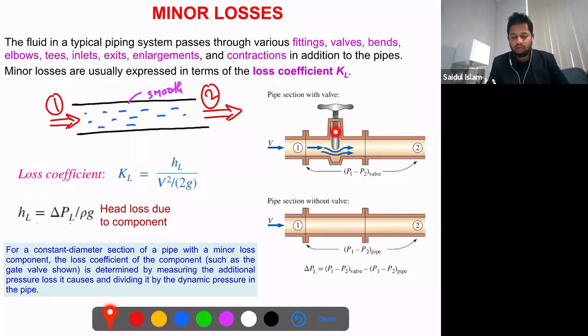So when it happens, it acts like a fin, some sort of resistance. Flow cannot just pass it, but needs to deviate due to this obstruction here. So what usually happens when we insert this sort of valve, we can see some loss here. Basically, for this pipe, this area from here to here is the fluid flow surface area. But when we insert this valve here, you will see it reduces like this.